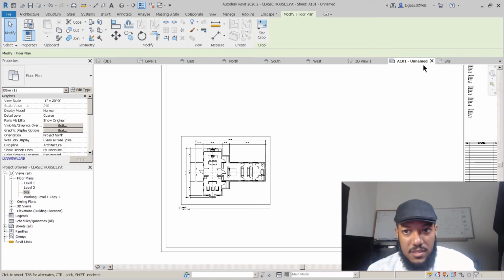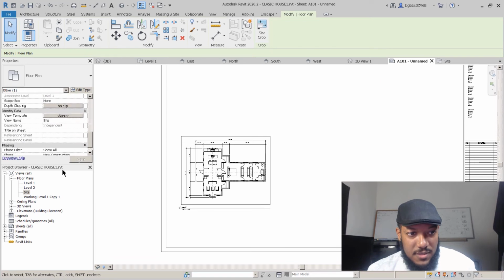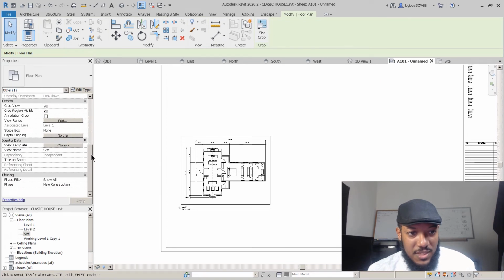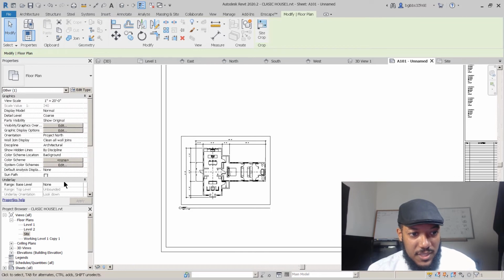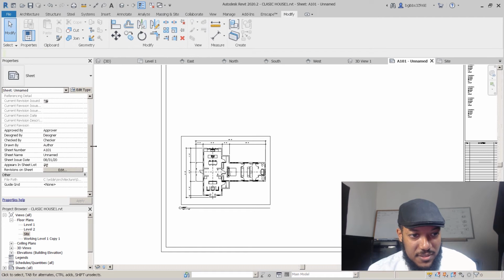Okay, we go back to the sheet, and we'll label this, and we go to our properties. We'll scoot down our browser, and we'll label this drawing. We click on the space, we'll see what its name is. It says sheet number here, and it says sheet name. We just go in here and say drawing set, and we'll put SD.